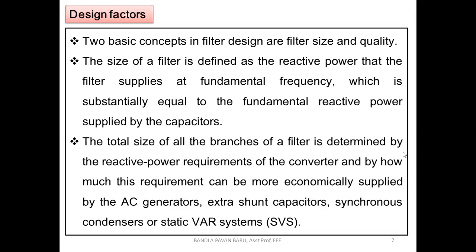Of course, frequency cannot immediately get varied. It is a rare case. But coming to the voltage, there are more chances of voltage variations, in the sense it cannot maintain constant voltage under running conditions. So in order to make it stable, we are going to compensate the reactive power, and all these are interrelated.